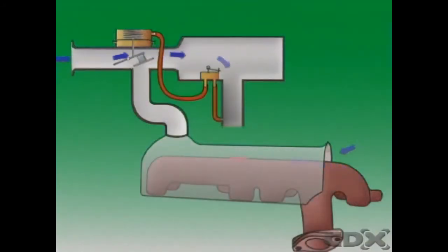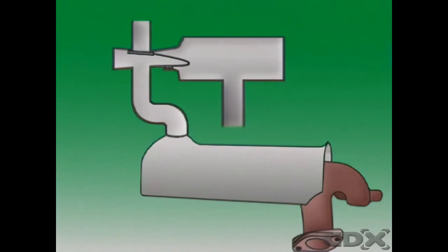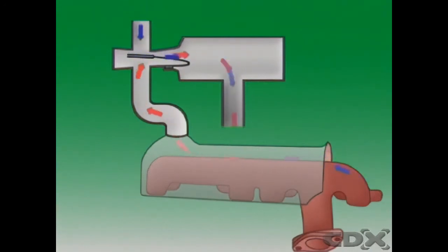Once an engine is hot, it may no longer need the incoming air to be hot. So the amount of hot air entering the engine needs to be controlled. On vehicles with emission controls, air cleaners use a valve to control how much hot air enters the air cleaner. This valve can be a simple thermostatic type. When the engine is started, only heated air is used. As engine temperature rises, the valve opens and provides more and more air at normal temperature. This ensures that the temperature of the air supplied to the engine stays fairly constant.